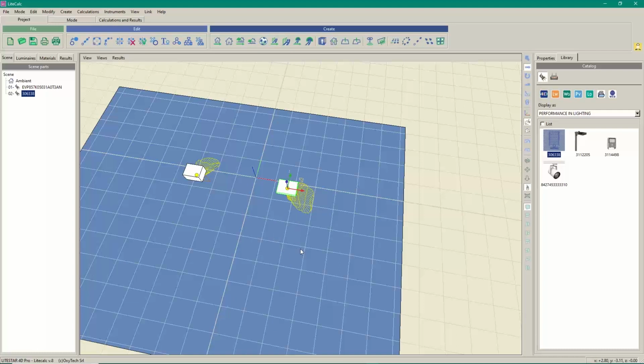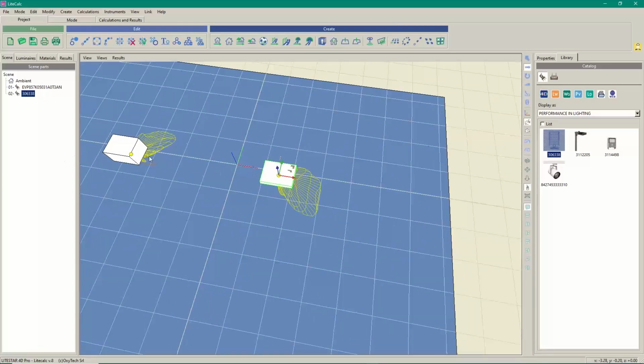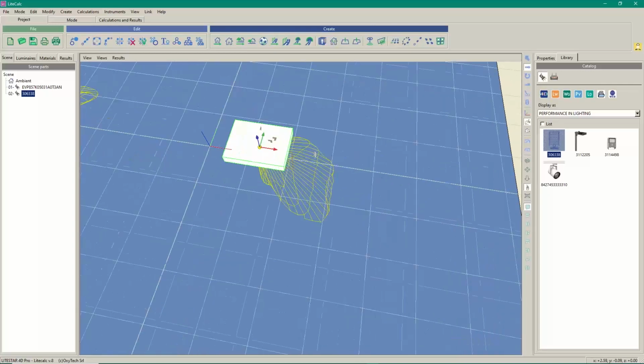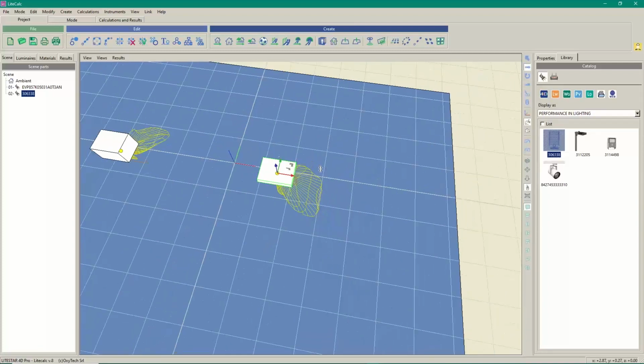So these are two asymmetric luminaires, but the aiming is difficult. You have to approach the aiming of these two luminaires in a different way, because otherwise you won't aim one of them in the proper way. As you can see over here, the luminaire has a little red square, and this one is showing where the C half plane is directed.